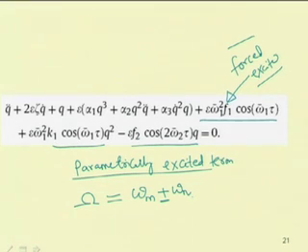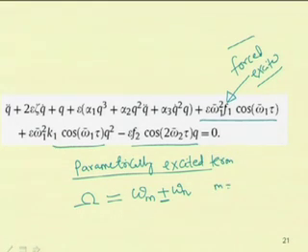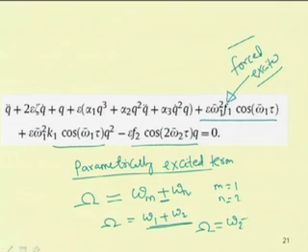Already you know for a continuous system you have a large or infinite number of natural frequencies. So, in this case if you take any two natural frequencies, for example, let m equal to 1 and n equal to 2, if you take omega equal to omega 1 plus omega 2, this is known as combination resonance of first and second type. Similarly, you can take the difference. So, you can write omega equal to omega 2 minus omega 1.